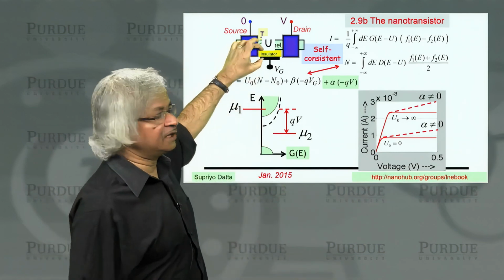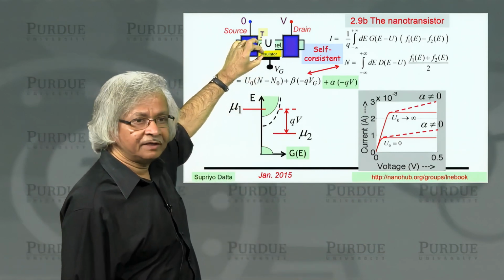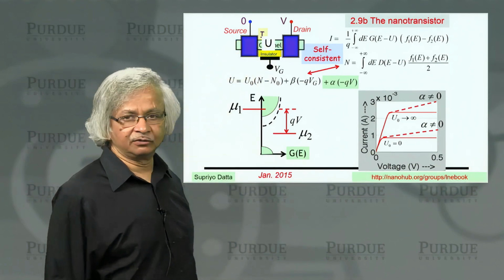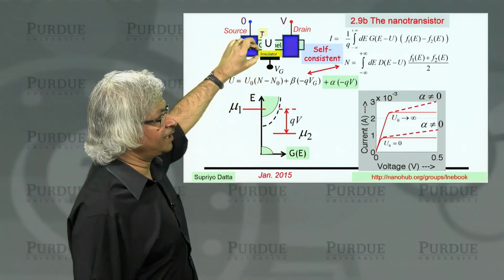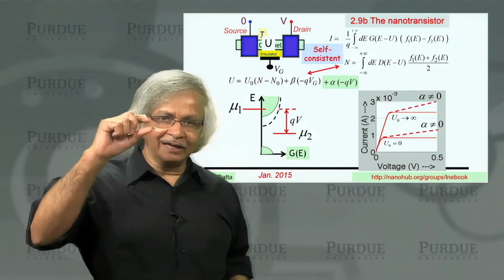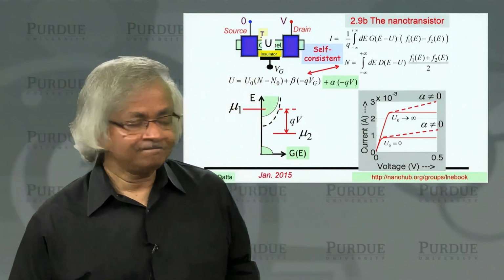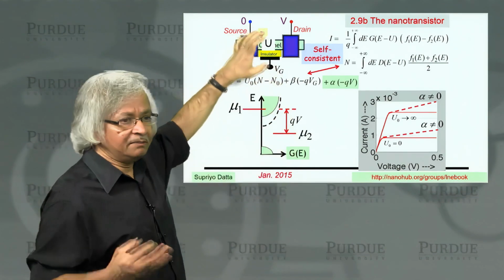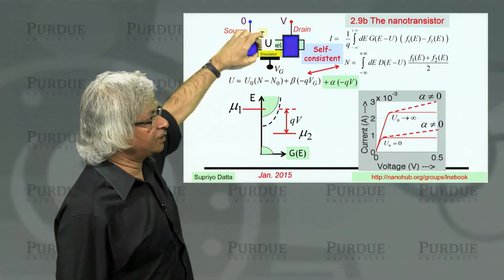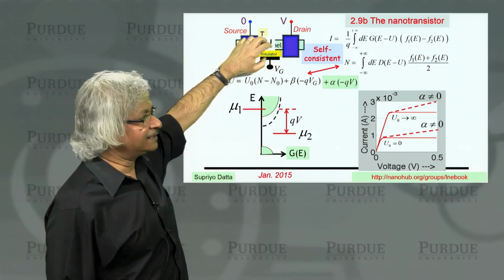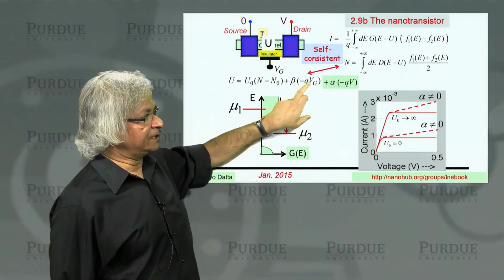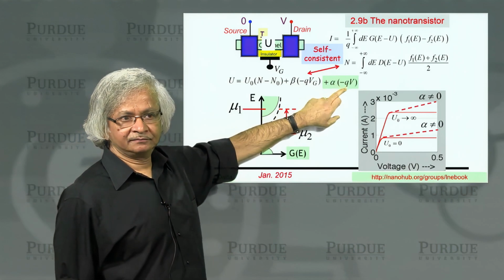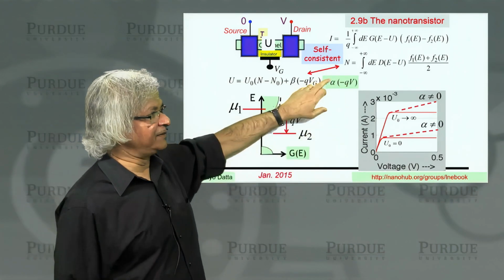And that, of course, is extremely hard, because once it's thin, it also means there will be more and more leakage currents as electrons tunnel through that insulator. Not to mention that it's very hard to control something to 10 atoms across billions of devices. So that really is the major engineering challenge, in terms of how to make billions of these nanotransistors work: how you can make the insulator thin enough that the gate controls the channel potential much better than the drain controls it. So that's kind of what determines a well-designed transistor.